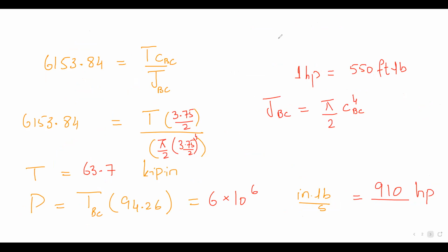You had a simple shaft, you were using 20 Newton meter of torque, you were happy. Now you had another shaft, the same size, but this time with a step. The shaft breaks, you're wondering, then you realize that you had to use the K value, because closer to that step, you had one individual stress line that exceeded way more than what you were predicting through TR over IP.